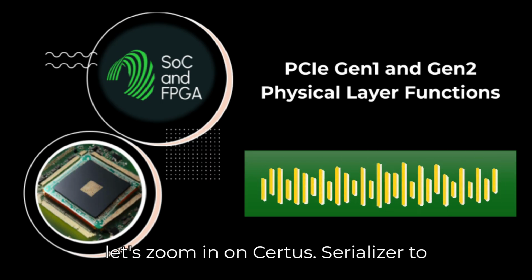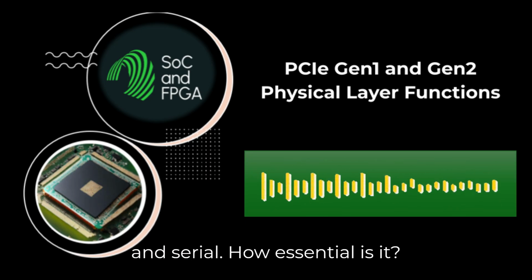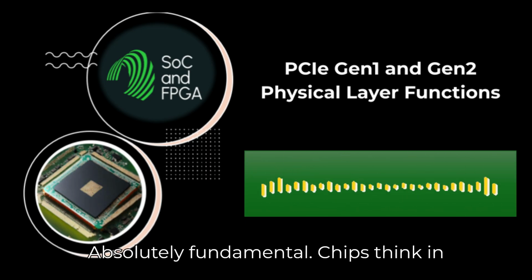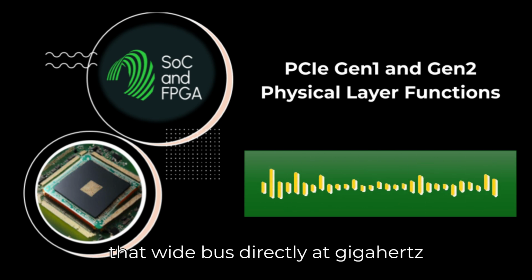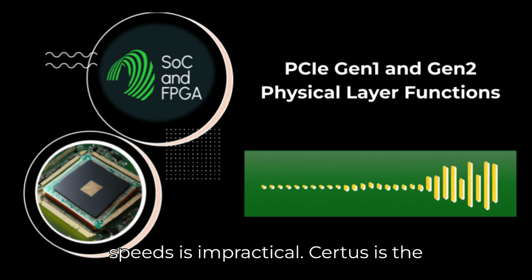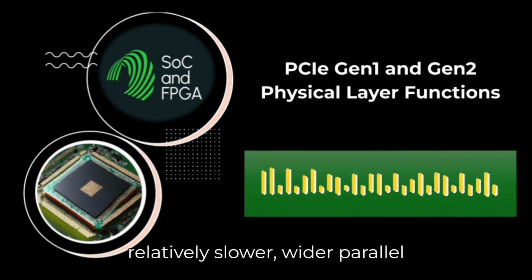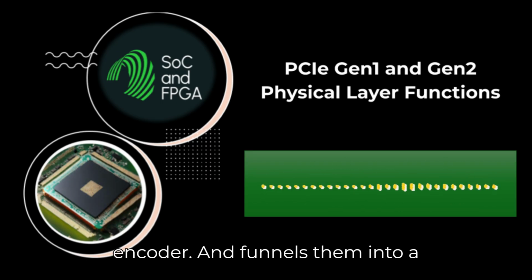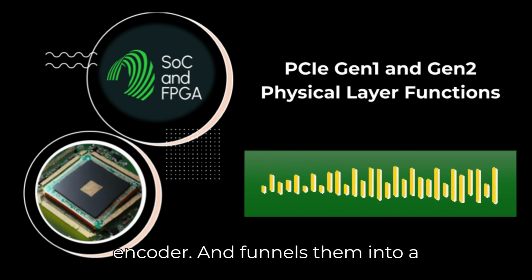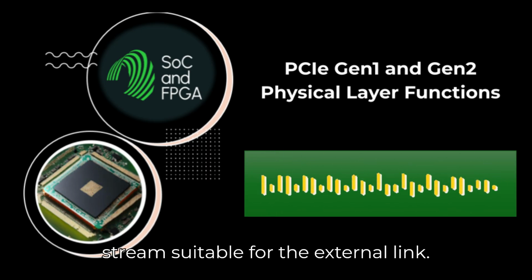Okay, let's zoom in on SerDes, serializer/deserializer. You said it bridges parallel and serial. How essential is it? Absolutely fundamental. Chips think in parallel, wide buses inside, but sending that wide bus directly at gigahertz speeds is impractical. SerDes is the translator. That's so. The serializer takes those relatively slower, wider parallel paths, like the 10-bit symbols from the encoder, and funnels them into a single, extremely fast serial stream suitable for the external link.